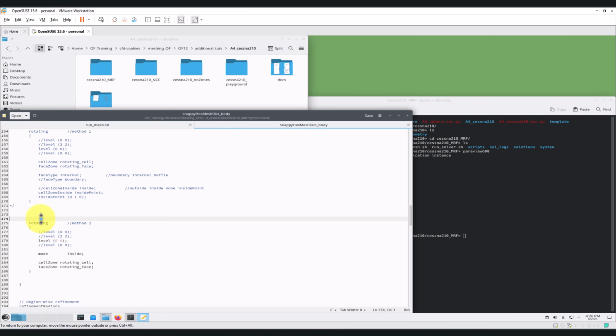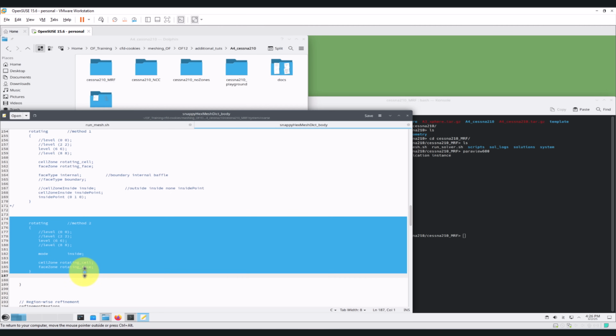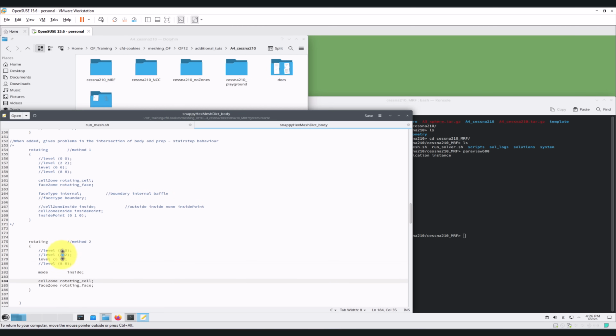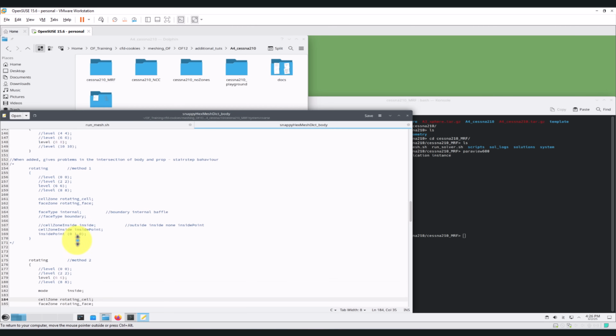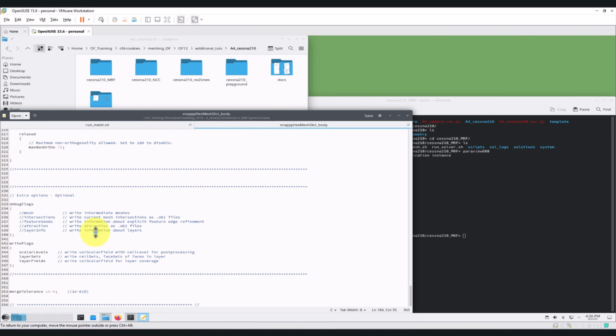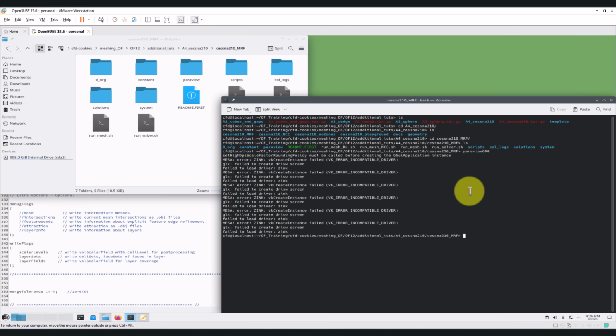So my advice now, when creating these regions, you do use this method. This is the easiest one. By the way, there is no limitation. You can have many regions. So if you have 3, 4, 5 propellers, read your geometries and create your regions. Obviously, give each a different name, but that's it. Okay. At this point, nothing else to do. Pretty much the rest is the same. So let's create this mesh, and let's see our results.